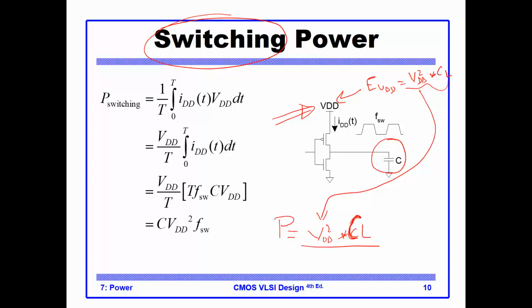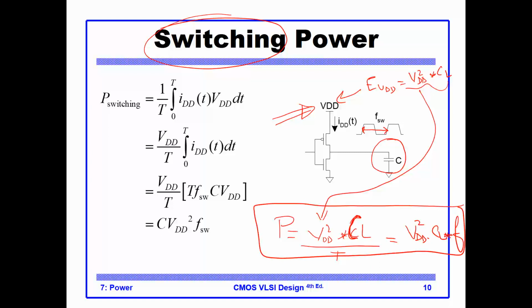We will take it from the clock period, and it is basically the clock period of the system. But there's an implication here when we divide by the clock period. The implication is that we are doing a charge every clock period, and this will lead to VDD square times CL times frequency. This is the power dissipated switching, so we'll call it switching power, switching this device.